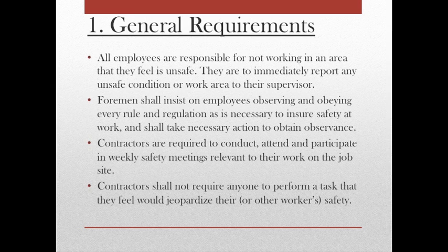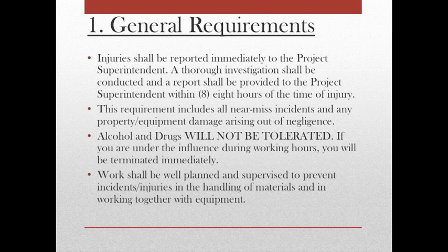Contractors are required to conduct, attend, and participate in weekly safety meetings relevant to their work on the job site. Contractors shall not require anyone to perform a task that they feel would jeopardize their work and or others' work safety. Injuries shall be reported immediately to the project superintendent. A thorough investigation shall be conducted and a report shall be provided to the project superintendent within 8 hours of the time of injury. This requirement includes all near-miss incidents and any property/equipment damage arising out of negligence.